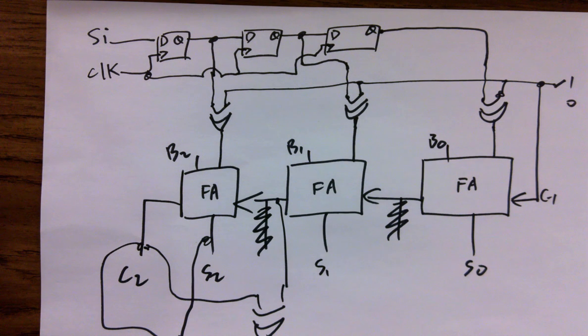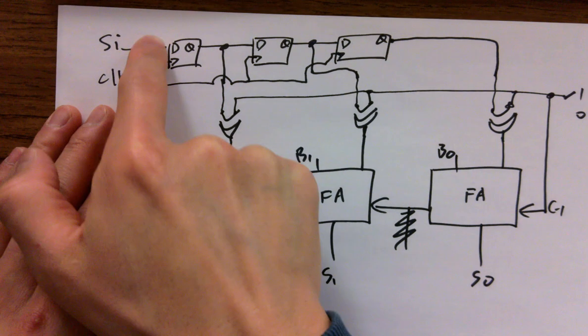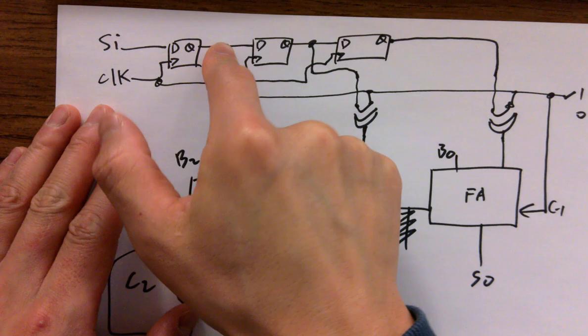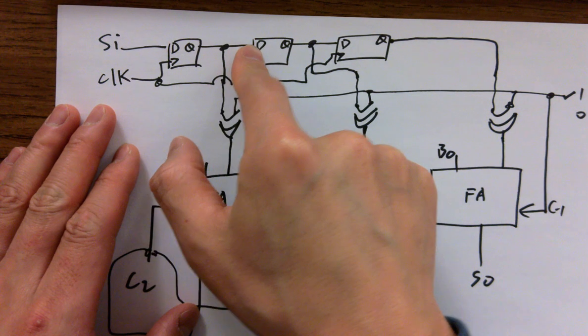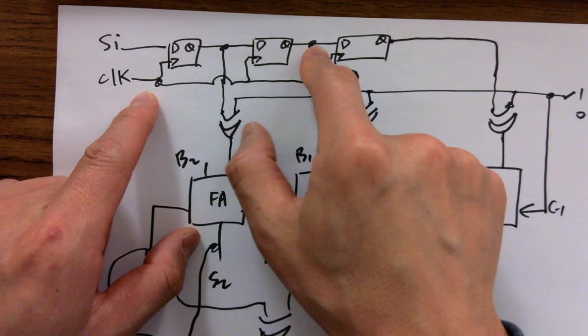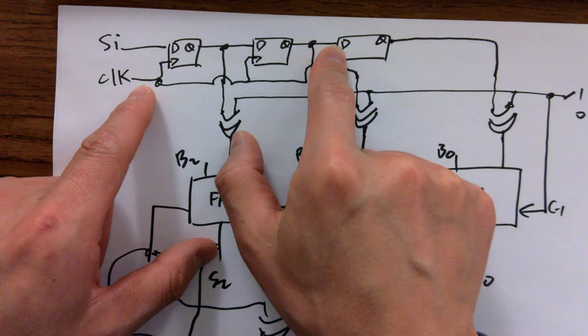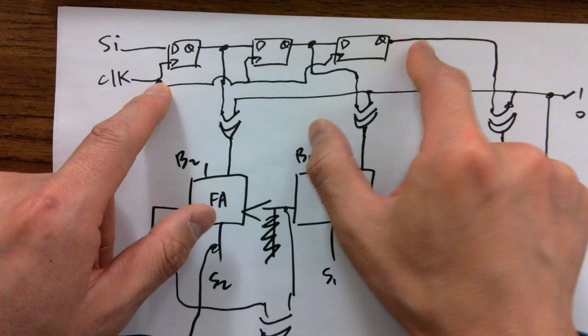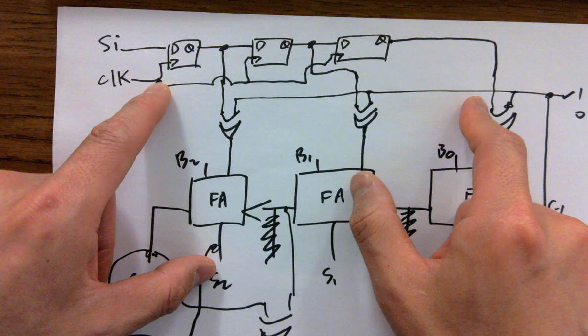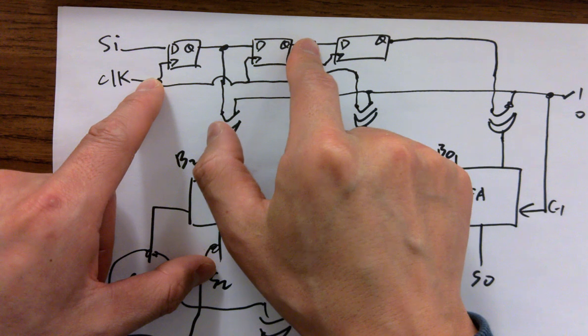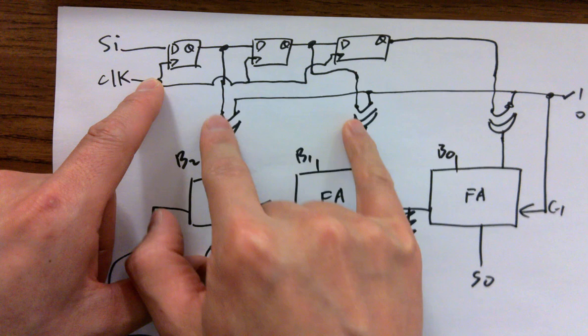So there's no parallel A anymore, keep in mind. You're not giving like 3 switches. These are not the static A's input. Nope. It's a serial in, it's digital serial data. You have to clock it into the register and parallel out. See? Serial in, you give a number, you clock it. Boom. Okay, so this becomes the D for the next stage. You clock it one more time, it's being pumped to another D. And you do it one more time, clock it, it passes to the final D, which becomes A0. And all the rest are being latched as these points and become A1, A2.